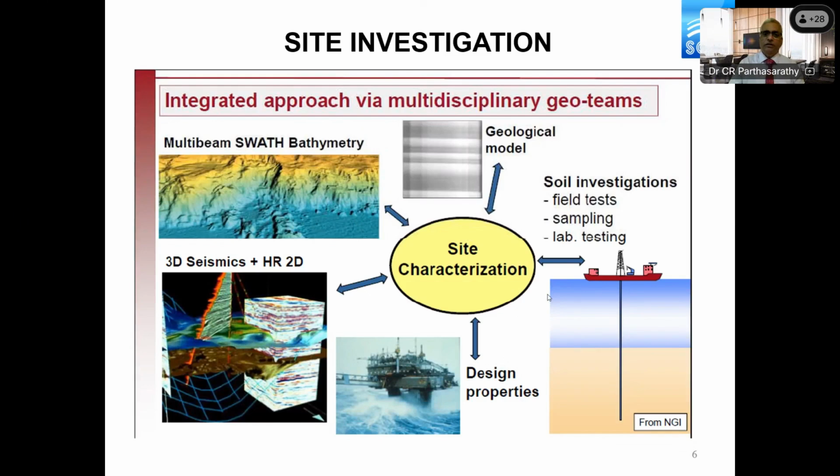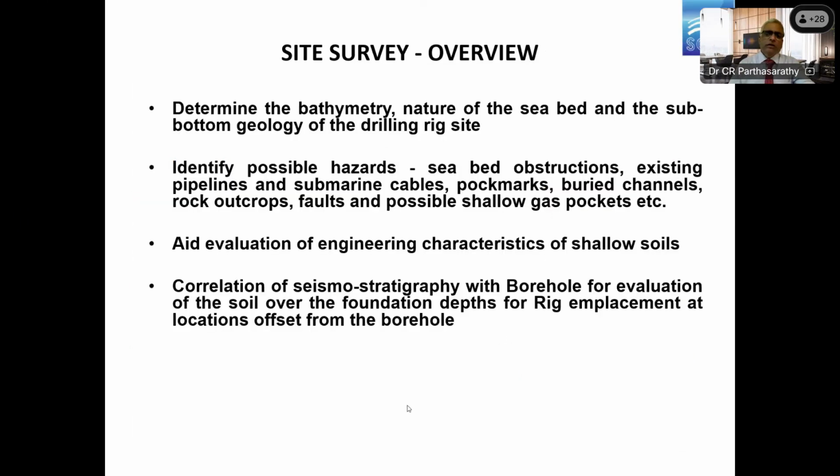Correlation of seismostratigraphy with boreholes is used for evaluation of soil over the foundation depths for rig emplacement at locations offset from the boreholes. So between the boreholes, the geophysical lines are drawn and the survey is carried out, and then you use the sub-bottom profiler to verify the lateral extent of continuity or discontinuity of the layers.